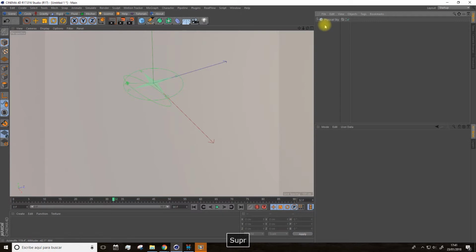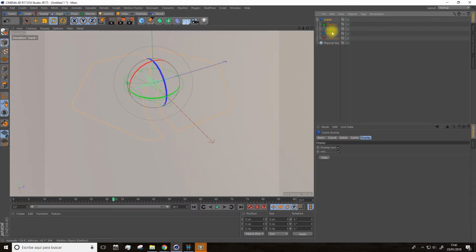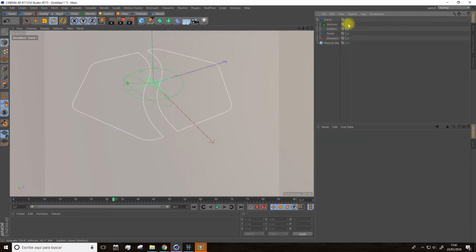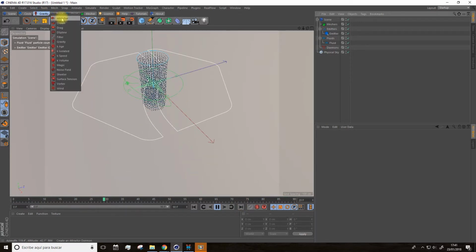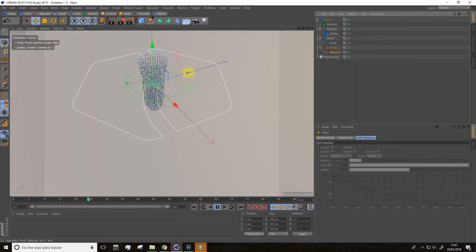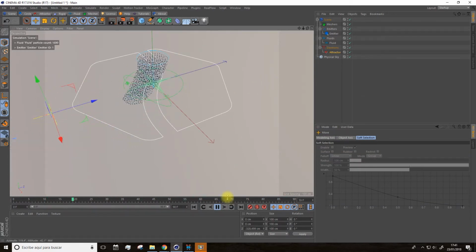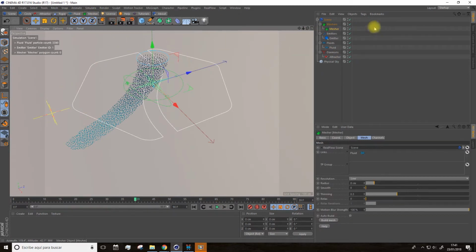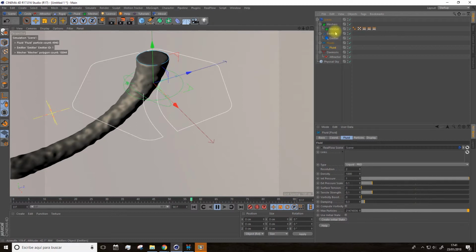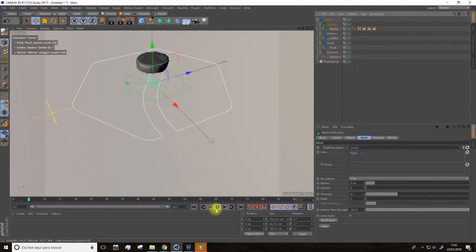We have the main panel, as I said, which is the scene. After creating a scene, a tree is automatically generated in the panel on the right. From here, we're going to start working by creating an emitter, any of them. We can also decide which daemon to apply, like, I don't know, gravity or attractor, for example, which attracts particles towards a surface. Then we would add a mesh to make this liquid visible, like that. The next step will be tweaking the fluid and the mesh's properties.